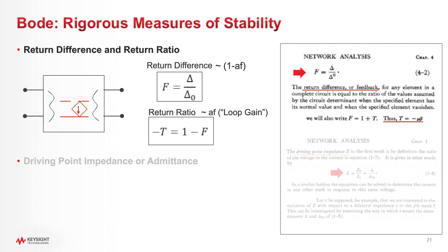Well, Bode in this work guarantees a stable denominator. So he basically is looking at encirclements, and if you're looking at the denominator, you'd search for zeros. If you're looking at the transfer function, you search for poles. But he's looking for only one of those things because he zeroes out the other term.